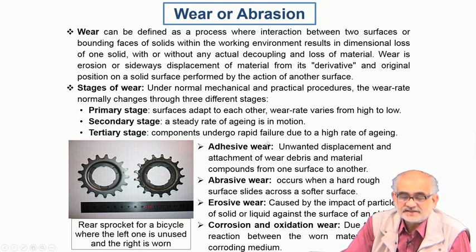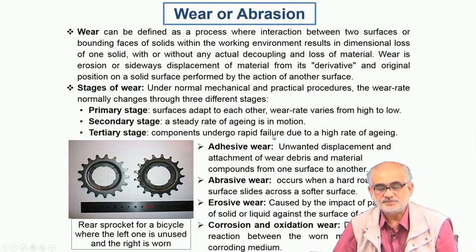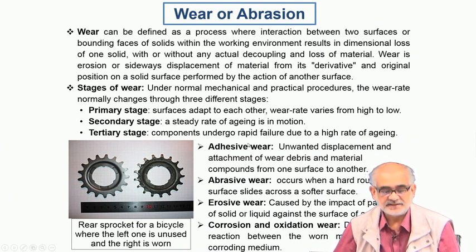And in the tertiary stage, again the friction goes up, because by then we would have accumulated a sufficient amount of debris, and for whatever reason there could be accelerated loss of material from the surface. But all these processes of primary, secondary, tertiary, and so on essentially depend upon the application of the load, the degree of loading, the contour of the two surfaces, the presence or absence of lubrication, the speed at which the two surfaces are gliding past each other or rotating against each other, and so on and so forth.